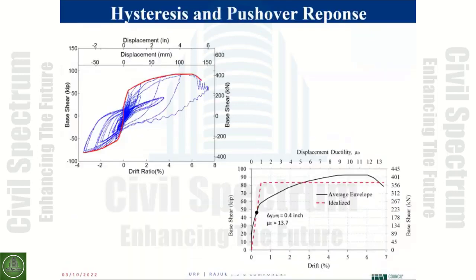Now, we tested this on a shake table. Again, to limit my presentation, I try not to have that many video clips here. But what's important here, let's look at the figure on the upper left. You're looking at lateral force versus the drift ratio of the column. First of all, you notice that you were able to develop large forces with a large, relatively high ductility. The drift ratio was over 6%.